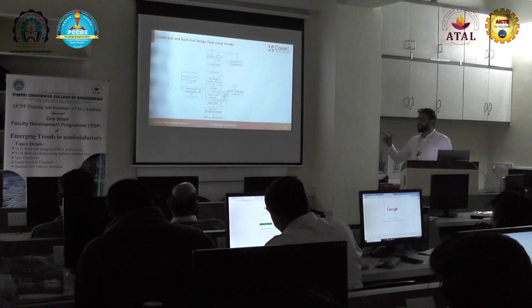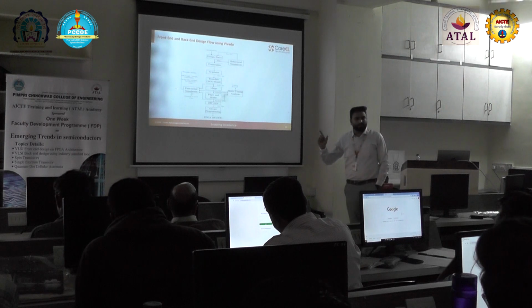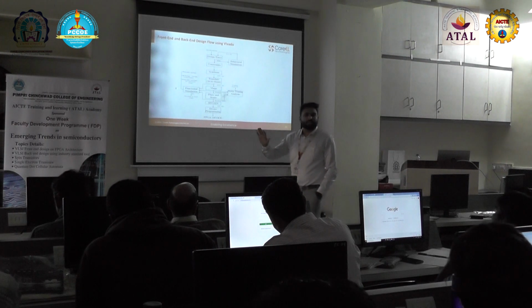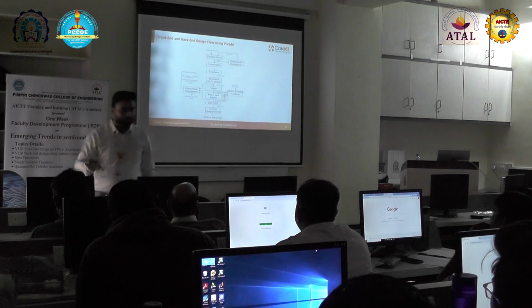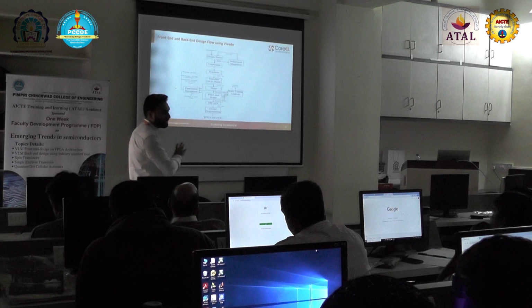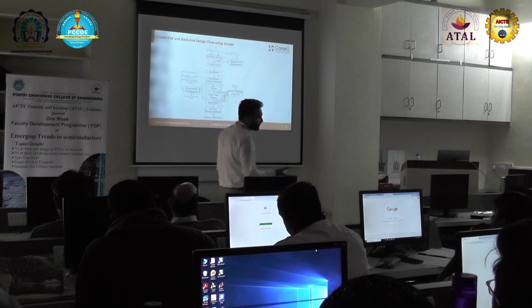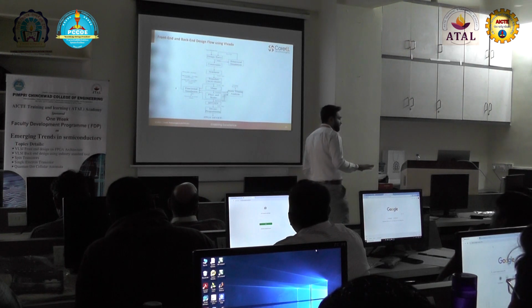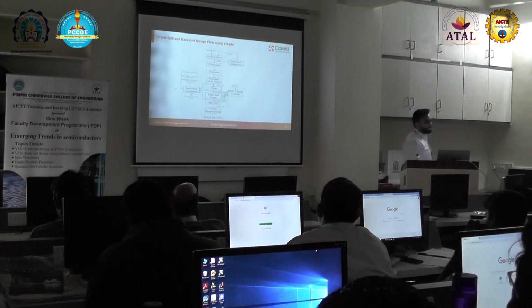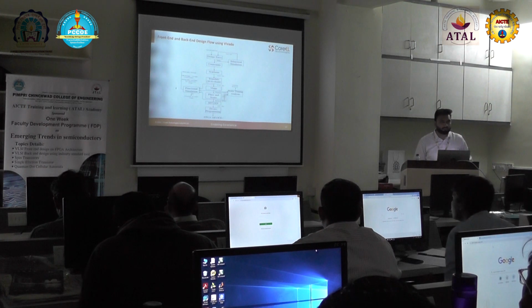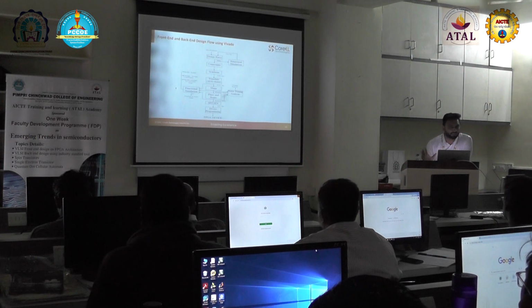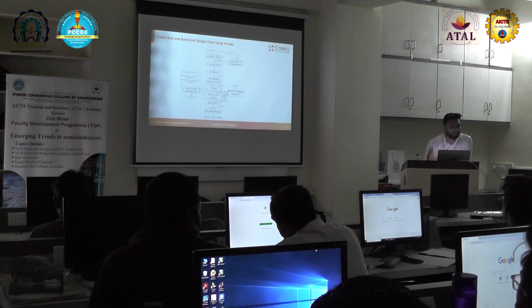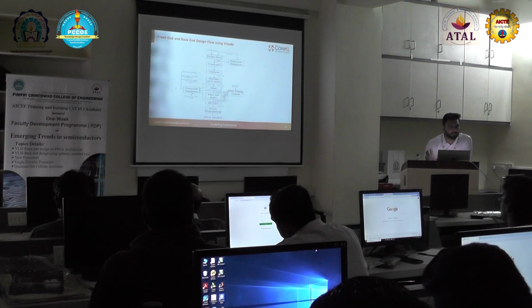Because in implementation, the placement and routing will be done here. So once the placement and routing has been done, there is no alternative you are going to do, no changes you are going to do. So once the implementation has been done, whatever reports you get, that is the final report. But when it comes to synthesis, whatever reports you get, that is not the final one, because that is just the estimation. Okay, this circuit will consume this much logic cells, LUTs. It will just give the estimation.